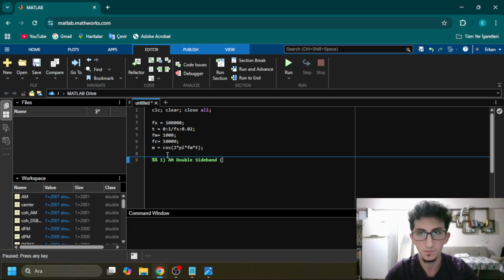Sideband, as we call DSB-LC, like that, and we are gonna define something again, and here in this part the modulation index Ka is equals to 0.8, controls the modulation depth.